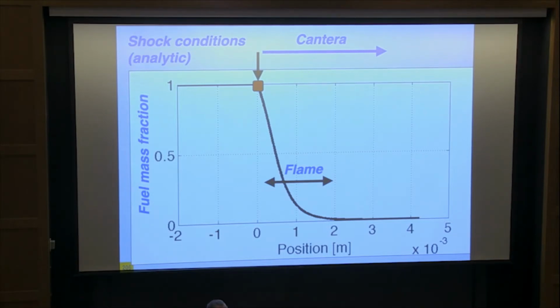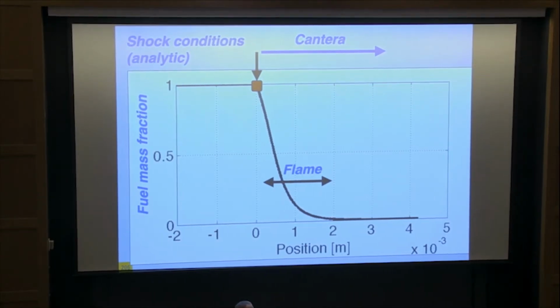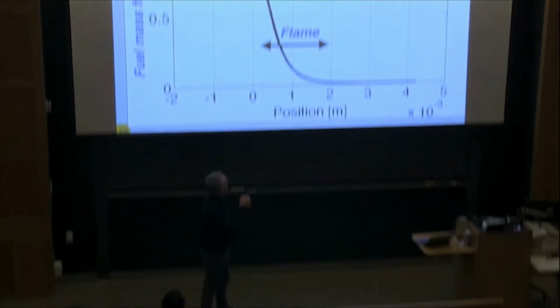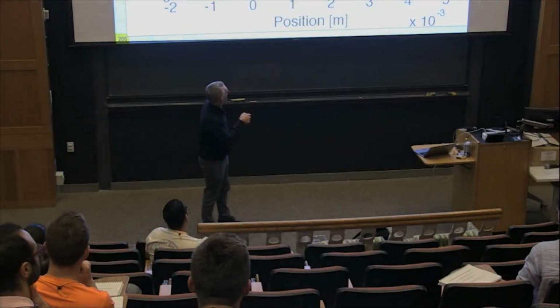And this one is controlled by kinetics. Okay, if the kinetics are slow, you're going to be too way long. And this is where you tune your kinetics, and the induction length is typically the distance you need after the flame so that this thing can start burning. And I didn't go into that. After that, this thickness, of course, will be important because it controls the size of the cells which develop on the flame front. And so when you match a chemical scheme in a detonation, you match the induction length. That means you match this distance here.